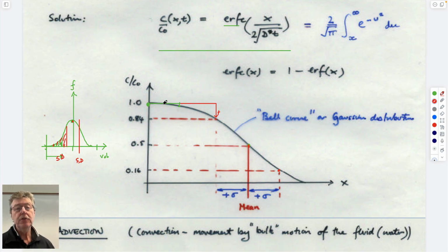So in other words, if you look at how a plume would spread, it would spread laterally over time. If you imagine holding this value to be 1 by supplying a constant supply at this point, then it would get flatter and flatter as it goes out, but it would never lose this peak. If you put, for instance, as we talked about, a drop of ink in an aquifer or in a beaker, this is a finite volume that you're putting in. This is the concentration over it.